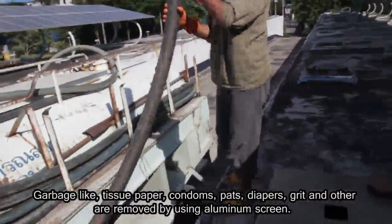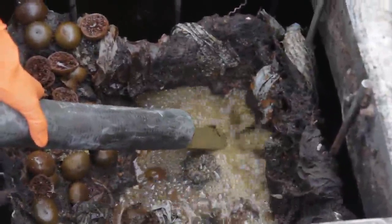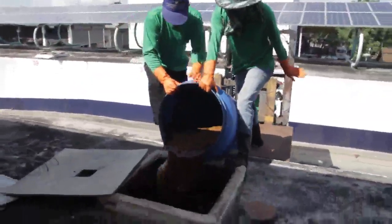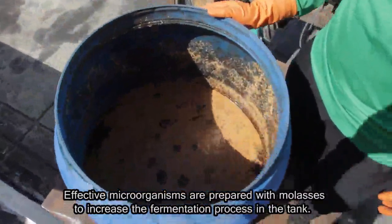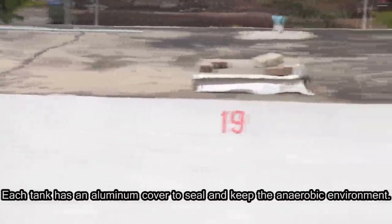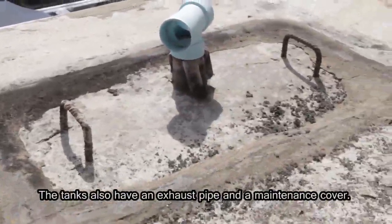Garbage like tissue paper, condoms, pads, diapers, grit, and other are removed by using aluminum screen. When the tank is full, effective microorganisms are added to the tank in a ratio of 1 to 200. Effective microorganisms are prepared with molasses to increase the fermentation process in the tank. Each tank has an aluminum cover to seal and keep the anaerobic environment. The tank also has an exhaust pipe and a maintenance cover.